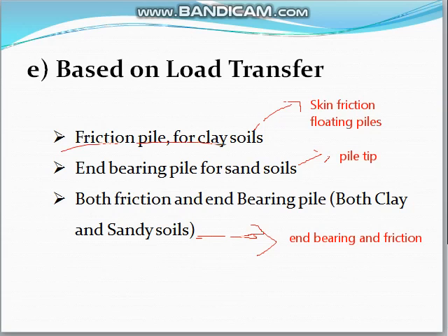Okay. Another one is the end bearing pile. Load is transferred to the hard strata through the pile tip. Used when hard strata or bedrock is available at a reasonable depth. These end bearing piles are also called point bearing piles.